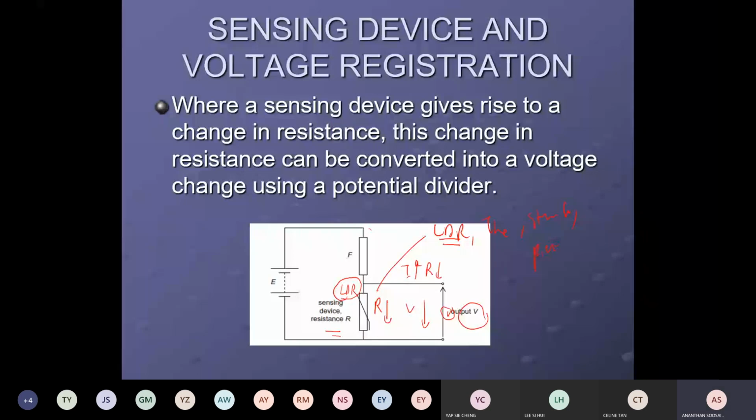Okay, thermistor, here in this diagram we have a thermistor. Thermistor, when the temperature rises, what happened? The resistance will drop. So voltage across the thermistor will drop. So the voltmeter registers a low voltage reading. And again, you go to the op-amp, and the op-amp will decide to switch on the alarm or not, because the thermistor is sensing temperature. If temperature rises, the op-amp will register a low voltage value. The op-amp will be connected to the alarm. Okay, somewhere there is a circuit to show.